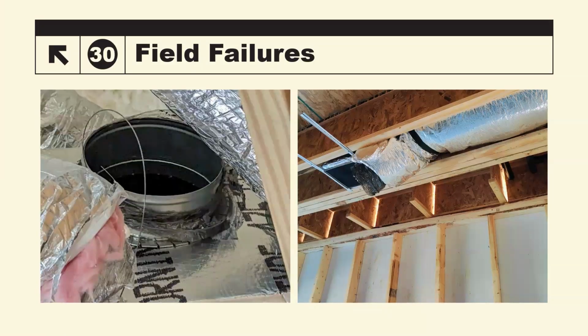And just a couple more here. We got no mastic on the collars, and the ducts, as you see on the right-hand side, are not connected on a subfloor duct. Once it's sheetrocked, there's not really accessibility to fix this. So this is one of those things where, unfortunately, you're just going to have to fail the test, not be able to pass it. They won't be able to sheetrock. You've got to wait till that's fixed.